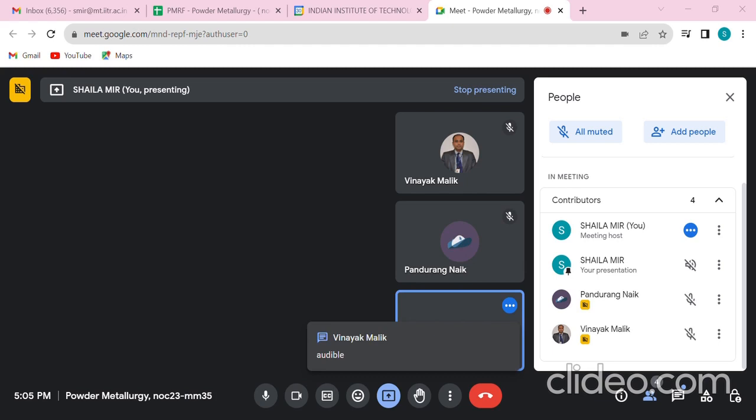And now all of these fabrication methods basically undergo these process steps. For example, when we are milling a certain powder, we are micro forging it. We are trying to forge it at a minor scale, at a minute scale. Once it is microforged, it gets fractured and certain cracks develop in this powder, and these cracks propagate, and as such we have two different particles of powders. And then there occurs agglomeration and deagglomeration. So these are the general process steps, or the general sequence that happens during the fabrication process, which involves majorly the mechanical milling.